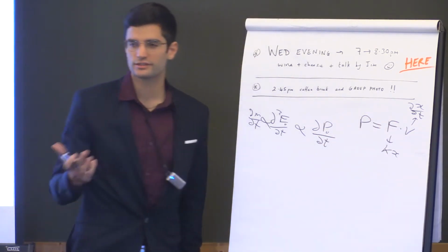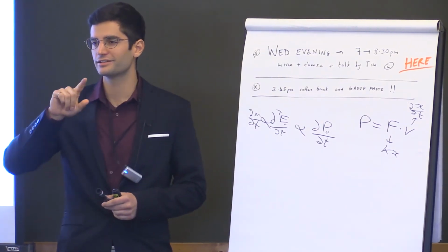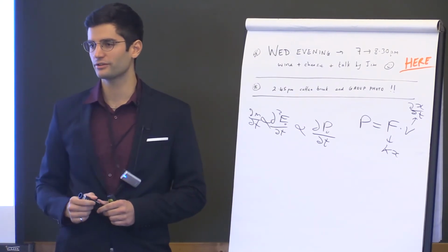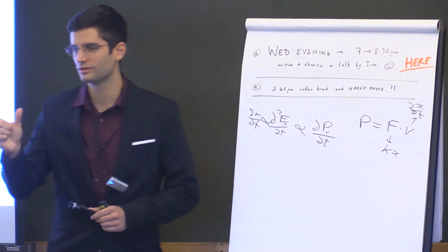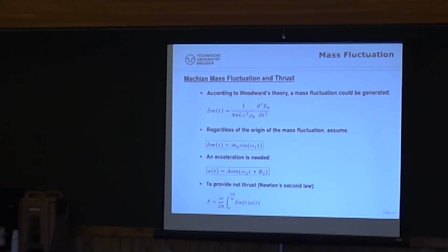And the velocity is just the first derivative of that amplitude. So you would get this squared component of that sine that you're driving the piezo at, and therefore you have that 2 omega in the mass fluctuation because of those dynamics. So the mass fluctuation has actually that 2 omega component.